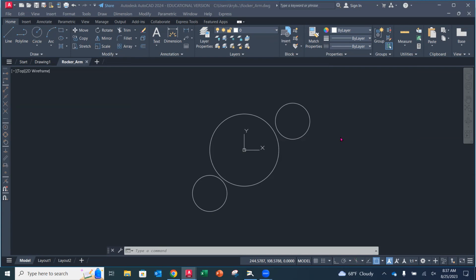So now we're going to turn the page and we are going to make these lines tangent. Okay. On the next page here on 214, they have you pull out that object snaps toolbar. We've already done that. It's available to us, but if you do need to review how to do that, it's there. But now we're going to utilize that line command, but we're strategically going to make this so that it's nice and smooth from one curve to another.